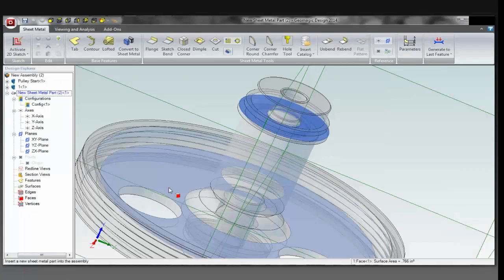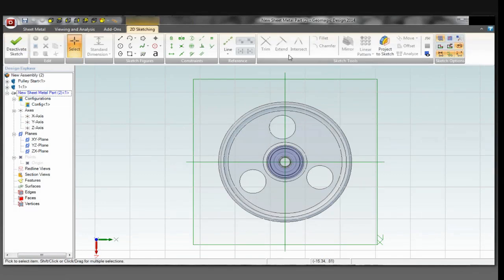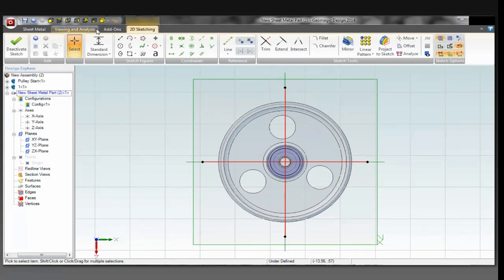So I'm going to create a sketch on that face. And since none of the reference geometry from that original sketch is actually going to carry over here, I'm just going to quickly create some reference geometry out of these two items here. And I'll delete those later. I just need those to help me generate this body real fast.